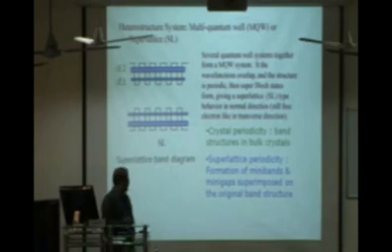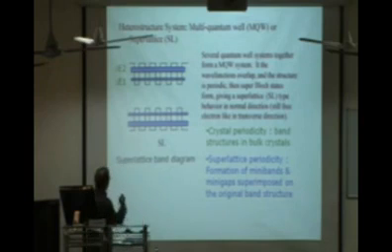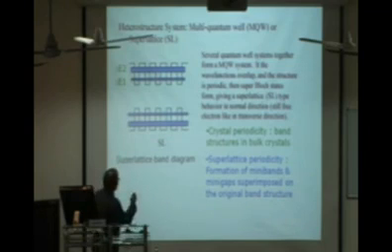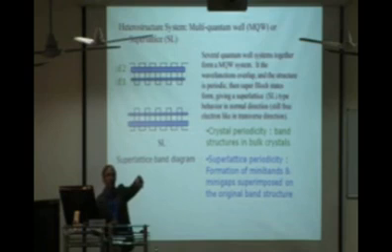But actually what is important is that you get something like this. Earlier you had only the conduction band and valence band. Now inside the conduction band, you get formation of subbands or minibands. And you see that in the conduction band you now have one miniband here and one miniband here. So there can now be electronic transport between these minibands.